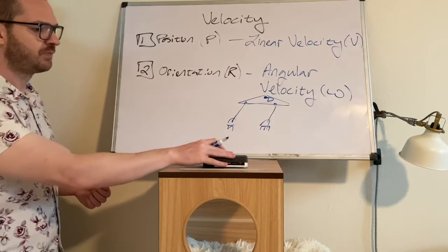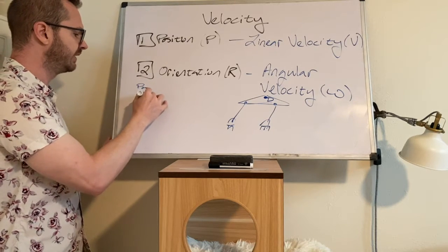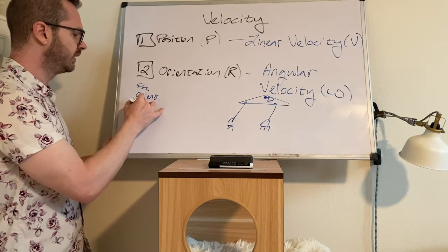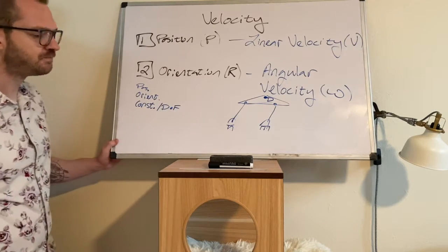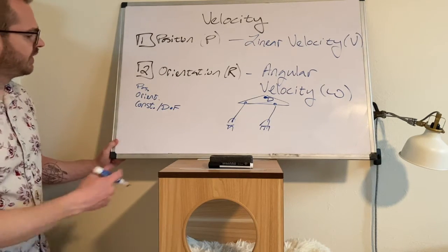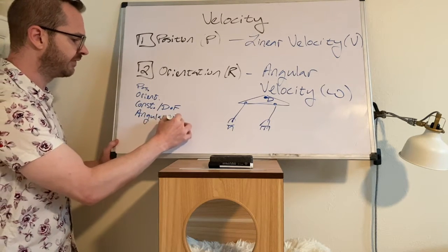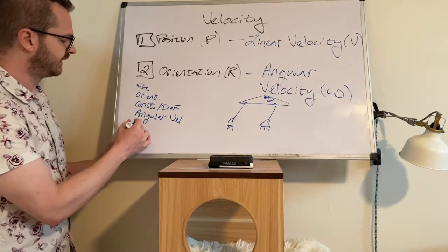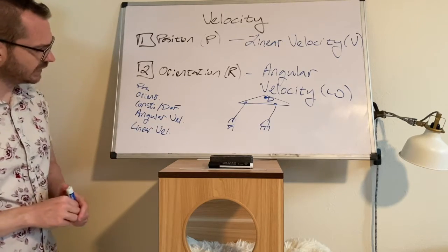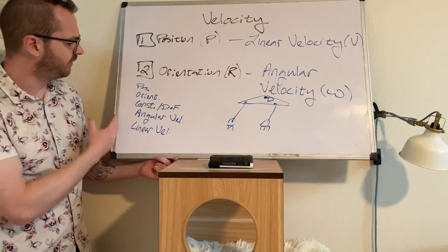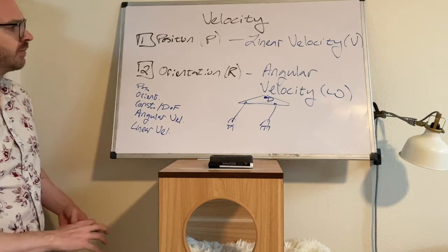The process for finding that, you still need to do position, you need to do orientation, you need to do constraints and degrees of freedom. And then, once you have answered these parts, I usually recommend defining angular velocity first, because it ends up being really simple, and then linear velocity next. Okay, so we're seeing this pattern develop, and this is going to be our recipe for the semester. If you follow these steps, you'll be able to do the dynamics for any problem.